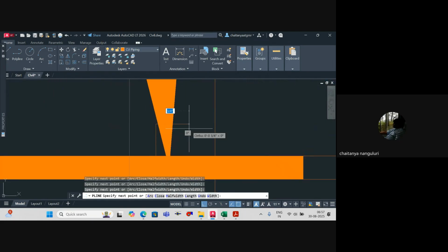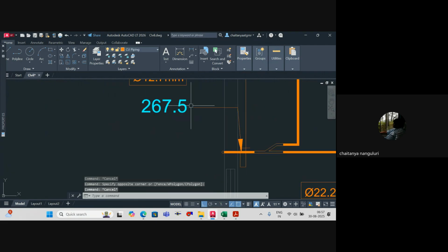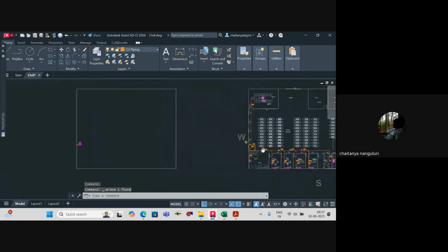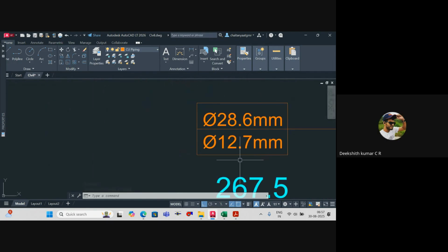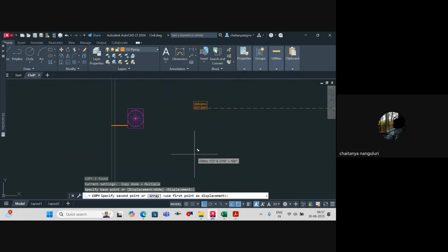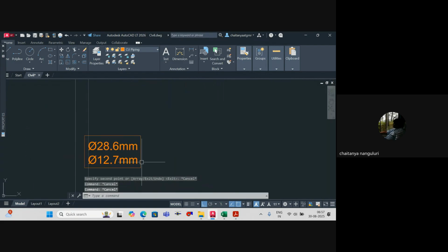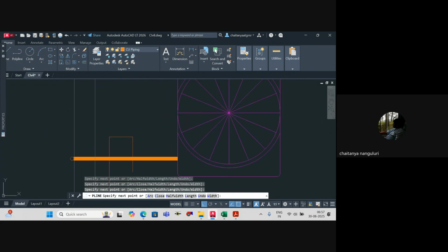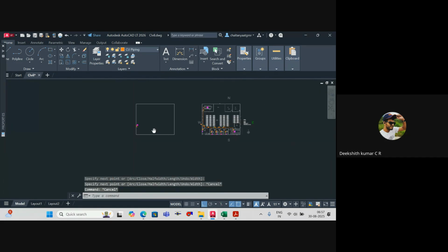This is your pipe sizes. That is nothing but the use of your capacity index. Am I clear? So your 12 HP outdoor unit, this is your pipe sizes that you have got. So that's how you do your VRF pipe sizing. Am I clear or not? You have to practice it.